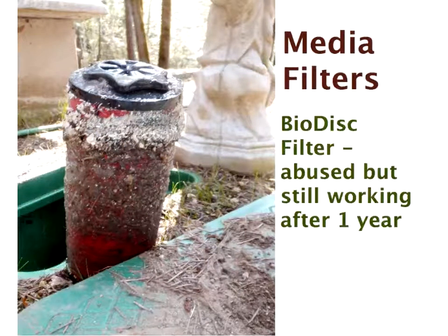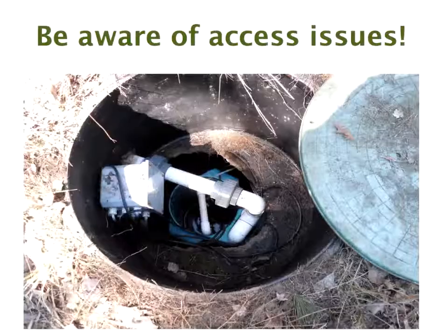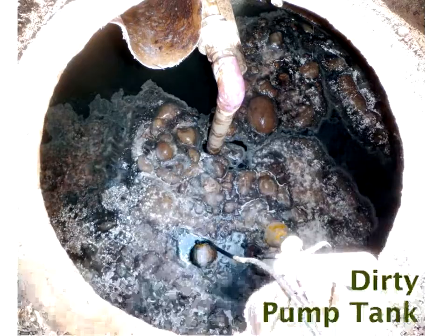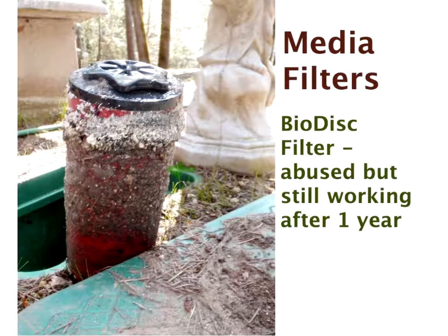Okay, remember I spoke about the biodisc filters. This filter was in this system. This was the pump tank that was supplying this filter. And believe it or not, this filter was still working. I found it hard to believe, but the filter actually was operating because the biological material did not manage to grow in between the discs. So that's why I'm so enthusiastic about this filter.